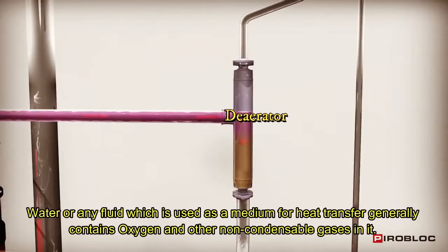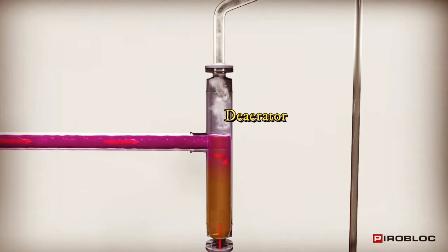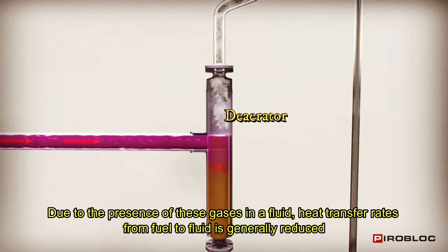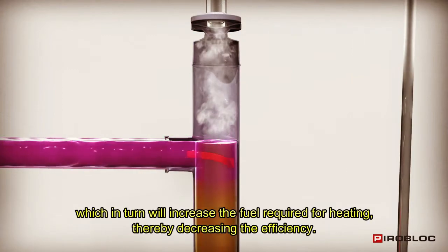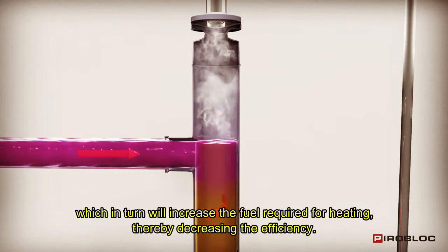Deaerator. Water or any fluid which is used as a medium for heat transfer generally contains oxygen and other non-condensable gases. These gases dissolved in a fluid act as an insulation to heat transfer. Due to the presence of these gases in the fluid, heat transfer rates from fuel to fluid are generally reduced, which in turn will increase the fuel required for heating, thereby decreasing the efficiency.